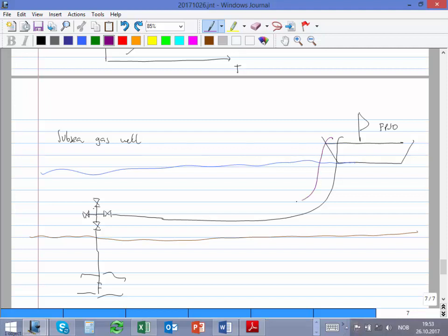I send another pipe down that has many other things besides the inhibitor, and I inject it actually here, with a valve. So that's the inhibitor line. And you can see why it's expensive, because you have one line that comes from the well, but then you have to send one line partly to inject this inhibitor, this methanol.